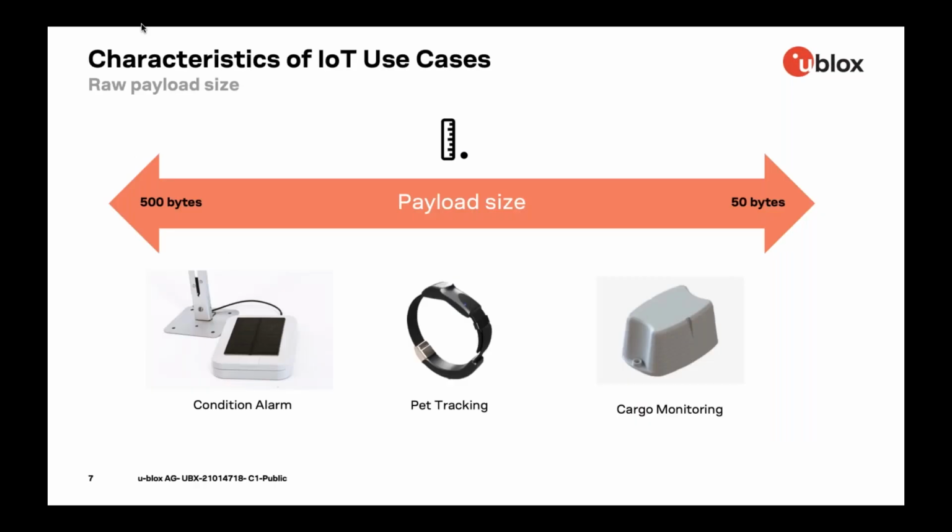Now, when we start thinking about IoT, obviously everything's being connected now, and when we start looking at some of the use cases, and we'll cover some of these in more detail specifically for these types of customers, we find there's certain characteristics, and this is very much where we're focusing. The whole solution these days is going to be around a couple of different parameters, payload size being one. When we're really looking at the raw payload size of what we're trying to do, it's typically sensor-based applications with IoT. And these sensors generate generally small payloads. They're trying to get an occasional measurement into the cloud. And so these are kind of our average ranges really when we look at what we work with, 50 bytes to maybe half a kilobyte.